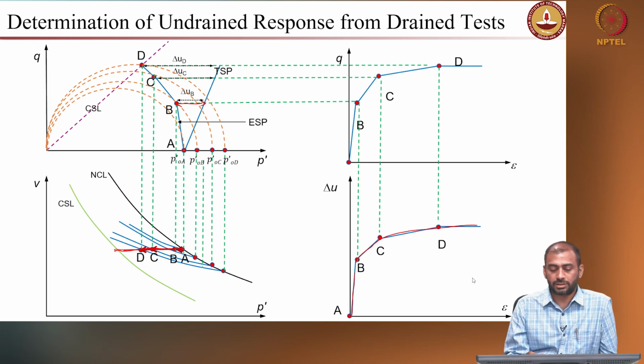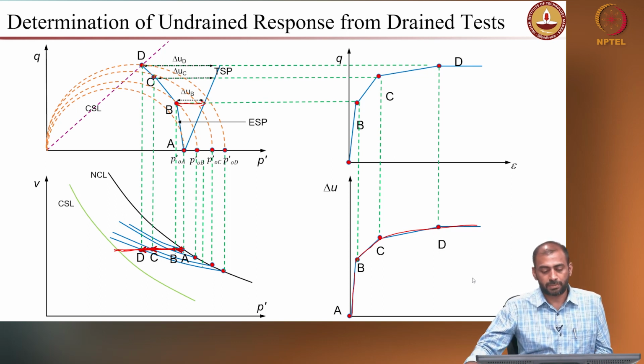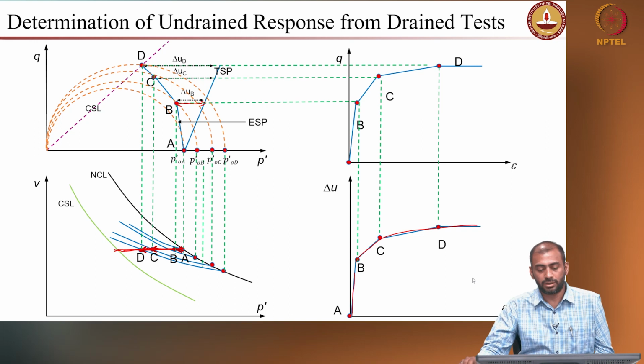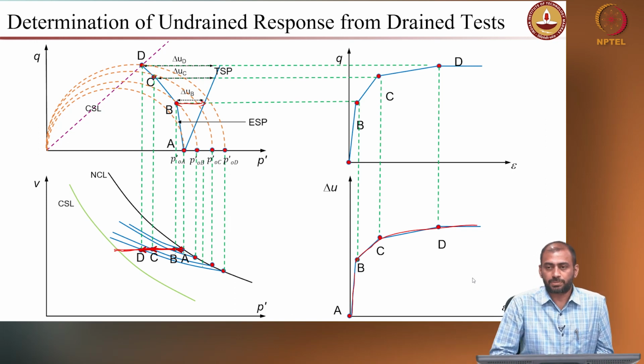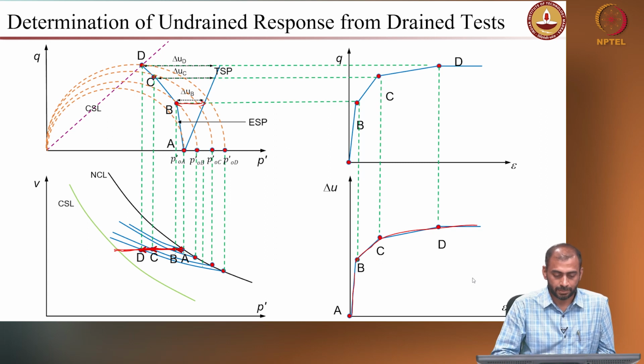This model, the original Cam clay and modified Cam clay model, predicts the material response fairly accurately, and it is capable of determining the drained response from an undrained behavior or the undrained response from a drained behavior.